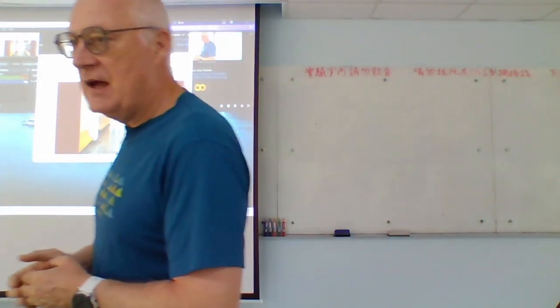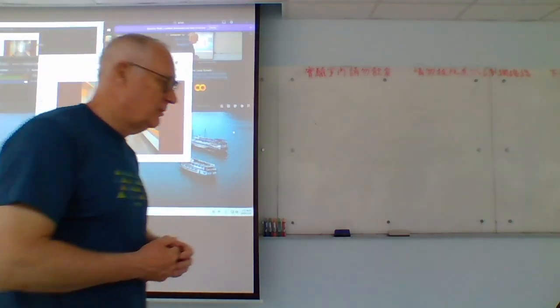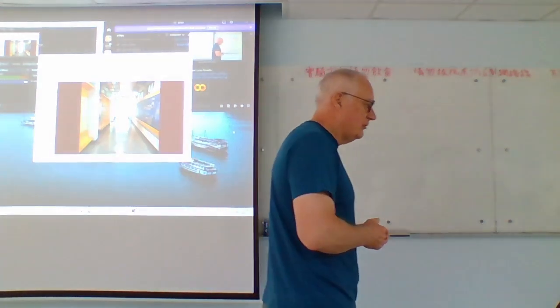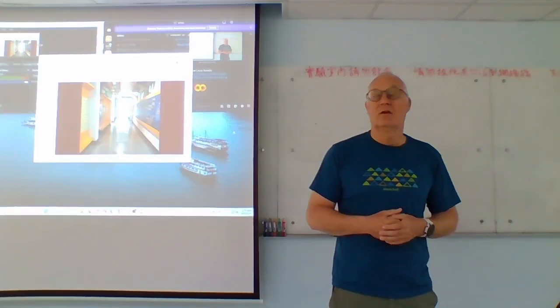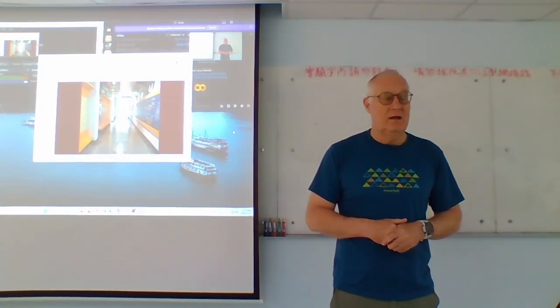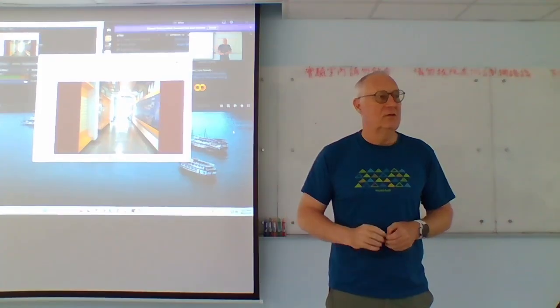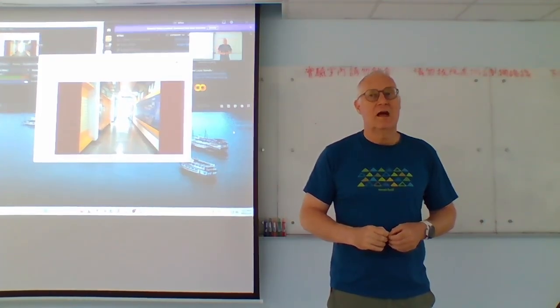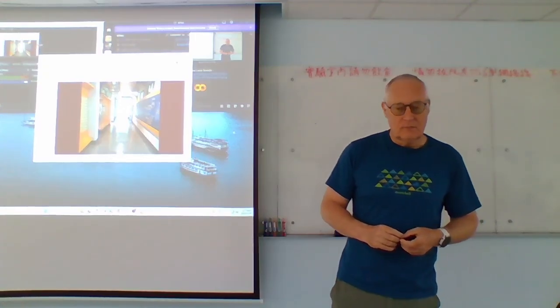We also have an IMU in the robot, which is an inertial measurement unit, which allows us to measure the angle. That's what we use in order to measure the current lean angle of the robot. It has a 3-axis gyroscope built in, so we can measure the angular rotational velocity, and it has an accelerometer built in.